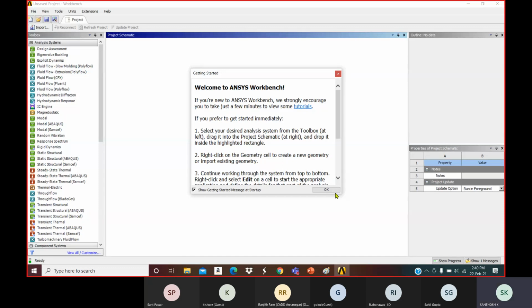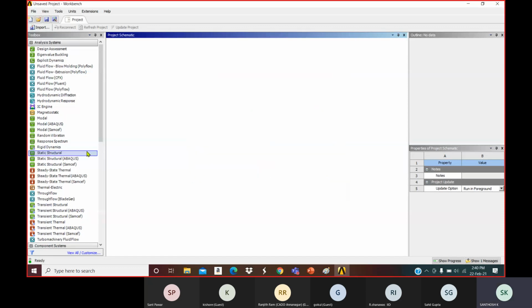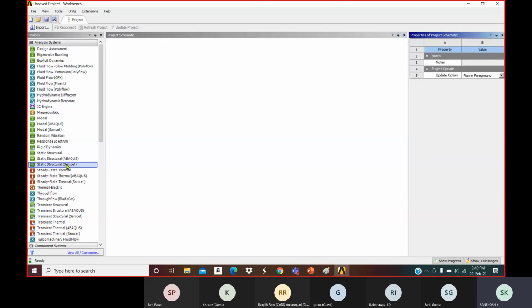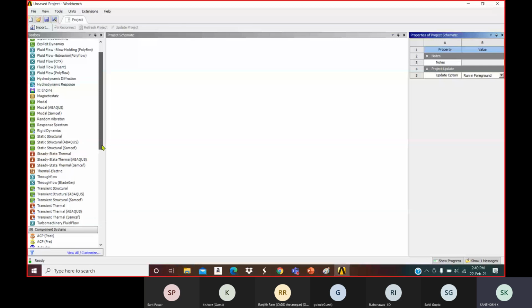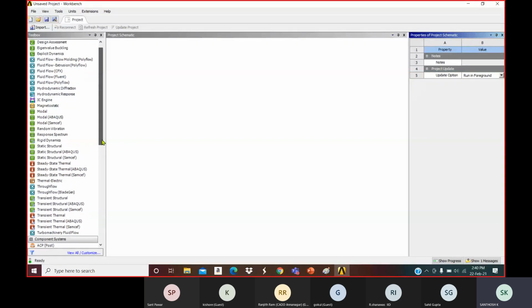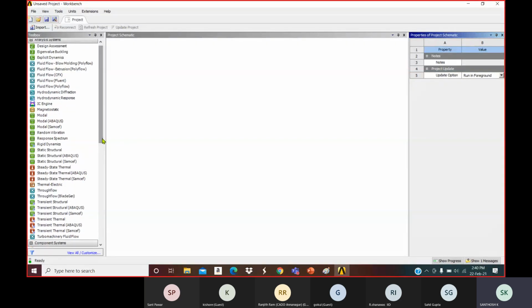Yes, so now once we are done with the application, go here. I think you all know Ansys Workbench, I hope. So what I do is I'll go here to Fluid Flow Fluent. From here you can browse it, or you can just drag and place it, or double click on that. I'll just drag and place it here.